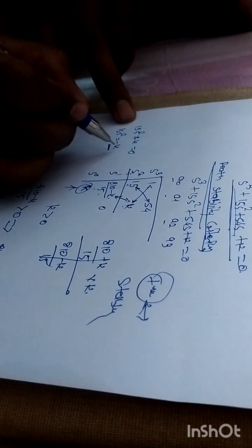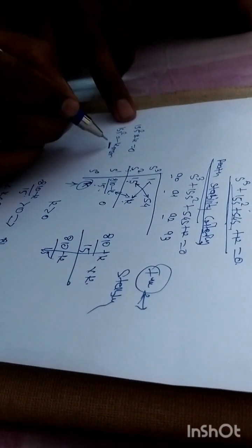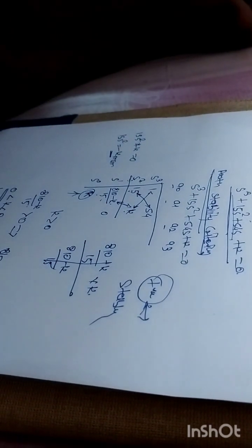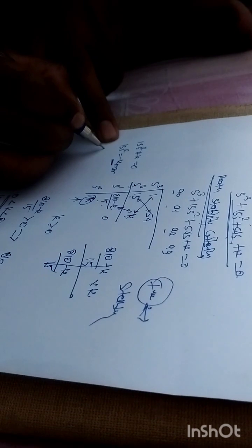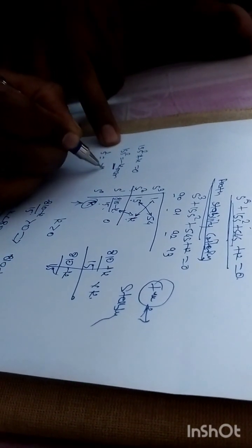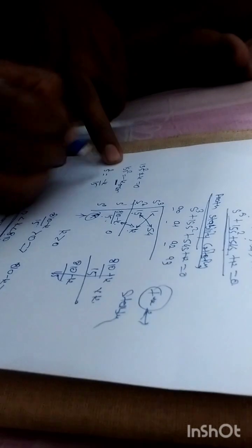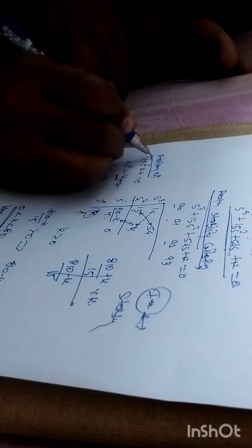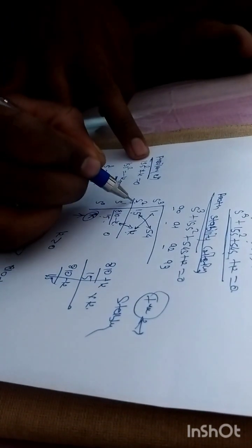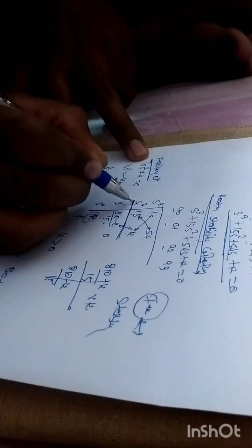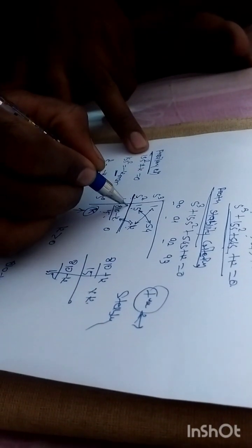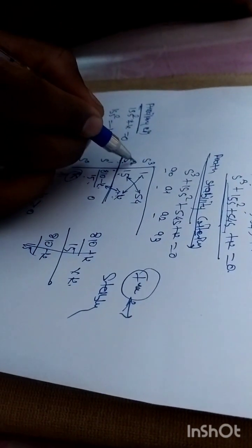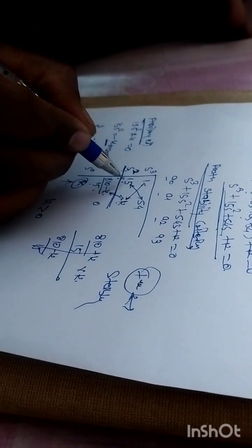Here the marginal k is the marginal value of this k. Already we have tabulated that the marginal value of k is 810. So s square equals minus k over 15. How is it being tabulated? From this auxiliary equation. How to get this auxiliary equation? For that purpose, we need to consider the elements belonging to the s raised to 2 row, or the row in which the power of s is 2. Those elements are 15 and k.